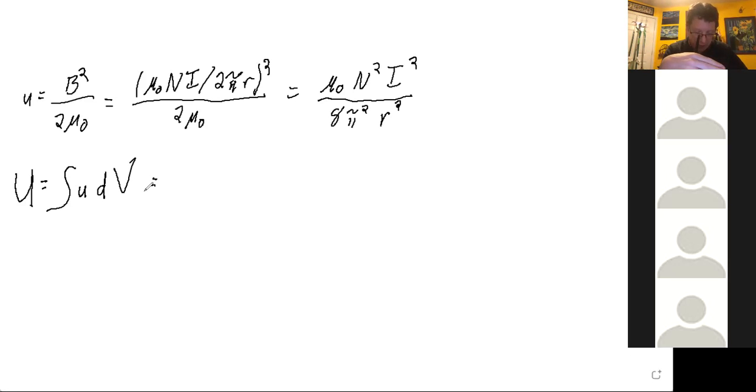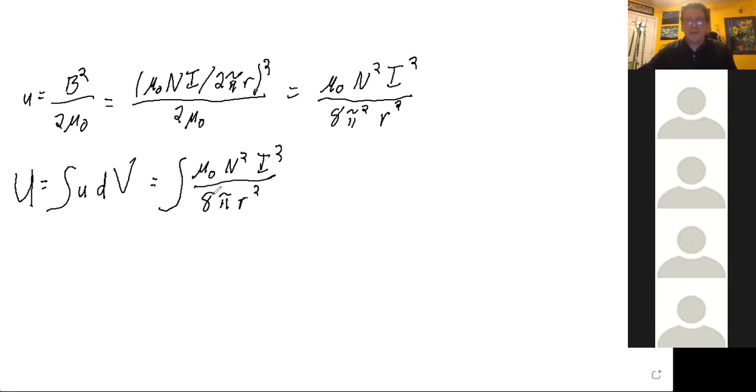So you have a circular cross section. So putting all these terms in, mu naught n squared I squared over 8 pi squared r squared. And most of this is going to eventually come out of the integral because it's constant. So you have the circular cross section. The differential element of an area of a circle is equal to r dr d theta.